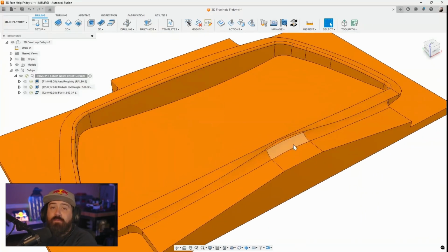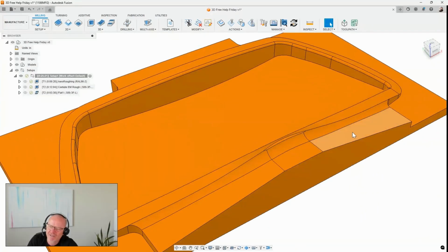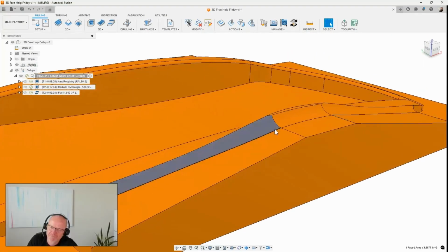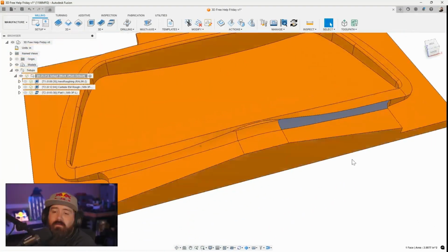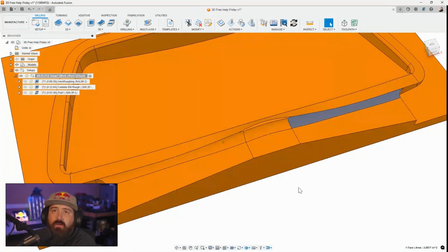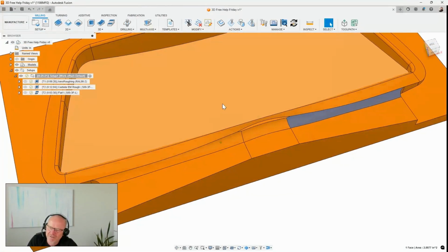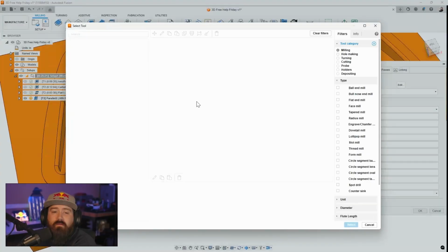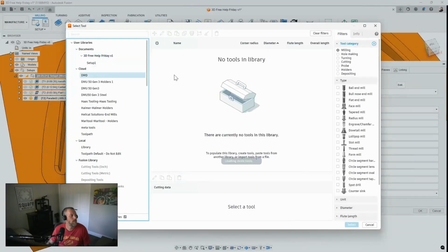We've got a 3-axis machine. So these are probably flat, but are they flat in those fillets? I think these are flat, but yeah, let's look at maybe this whole area here. Parallel would be super easy to do. Then you're not parallel for sure. ISO curves, yeah. Let's take a look at that. Let's go in here. Start simple. Parallel. Possibly even a blend.